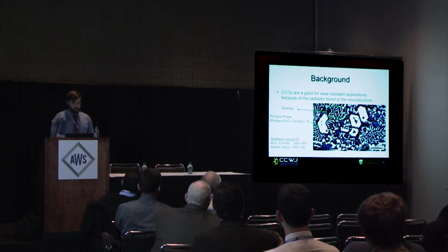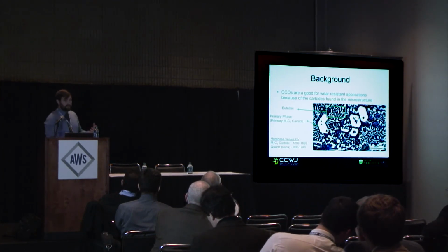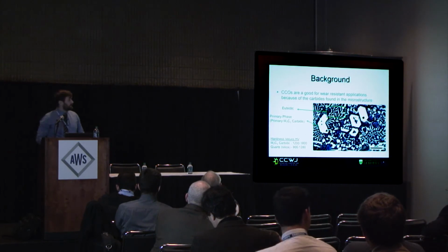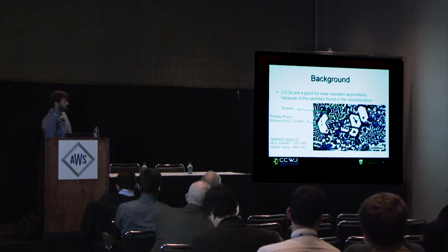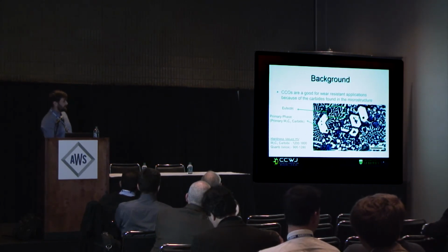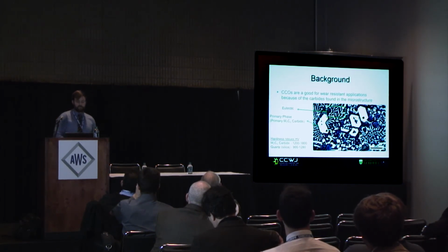And what you find is we use it as a wear-resistant material because the hardness of the carbide is much higher than that of, say, quartz or silica, which is 900 to 1200 Vickers hardness.